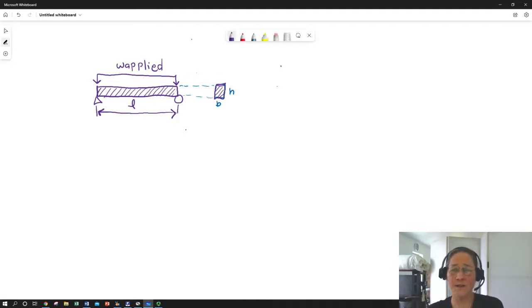We're going to assume that the beam has some kind of weight. A lot of our strongest materials are regrettably rather high density. So we're going to assume that our total distributed load is going to equal the sum of our applied load, what we are holding up with the beam, plus the weight of the beam, which I'm going to call a dead weight.